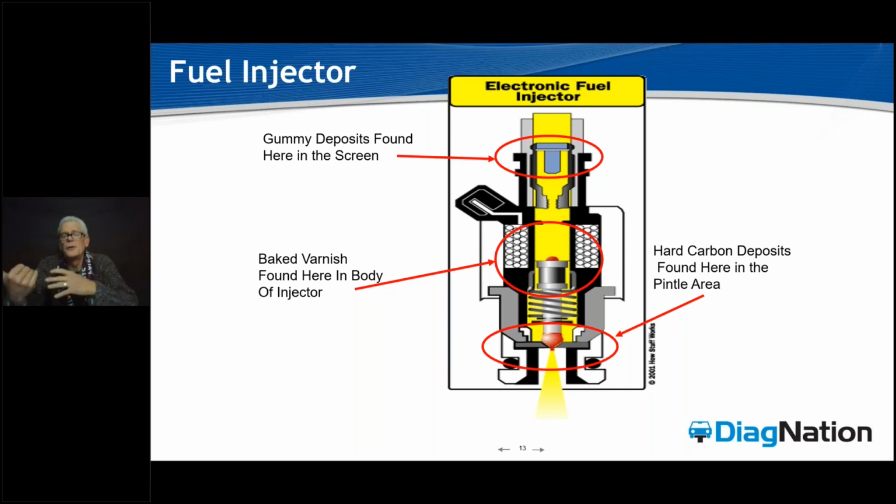It will move the deposit through that. Why? Because in that paraffin form, it's not like a grain of sand or dirt that the filter can catch. It's going to come through the screening, and it's going to start to load itself right here in the tops of the fuel injectors. Okay, and this is where we're going to start to see a problem.